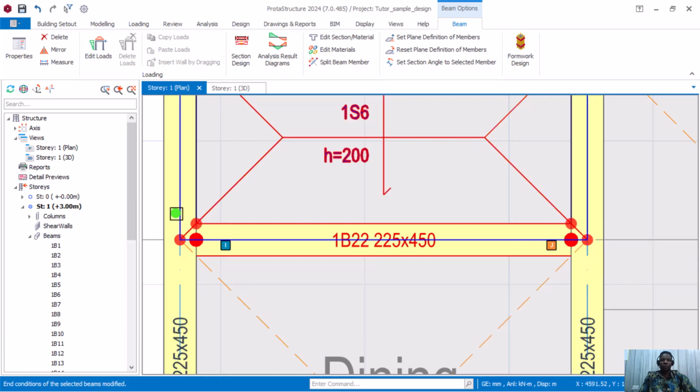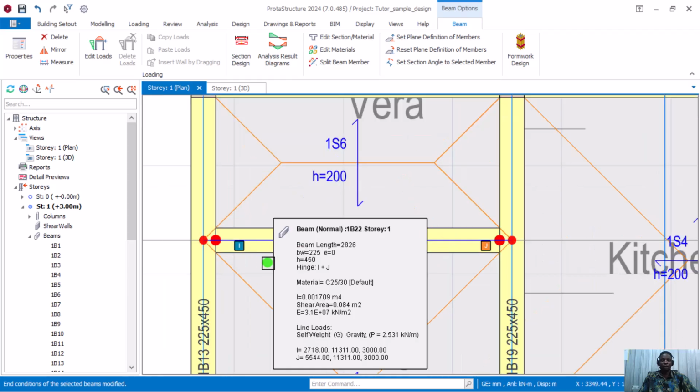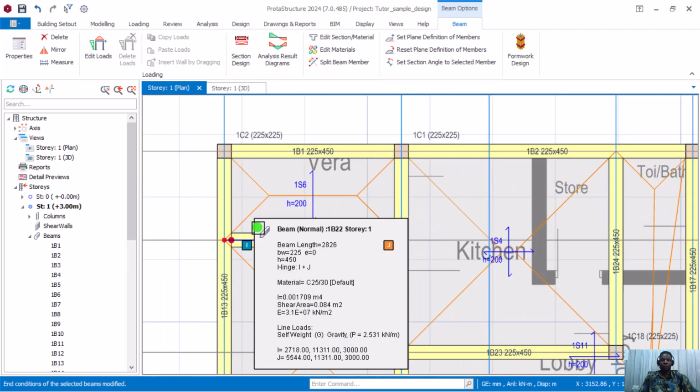But this other big one is telling you that you have hinged this beam to this beam, just like you're creating a connection. If you are doing a steel, that's what we call a connection, because if you place a steel on other steel without creating a connection, it's not going to connect. So in this situation, we are trying to make it fixed. And I believe you know that. So we don't want to make it pin. We have to make it fixed to that particular joint. Okay.